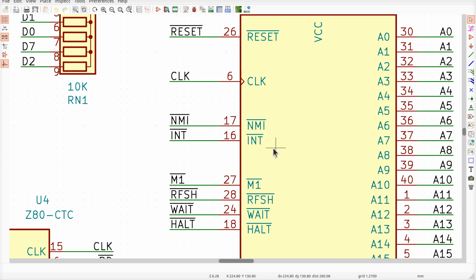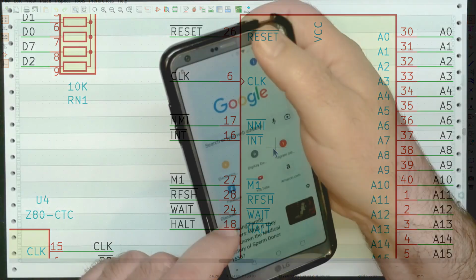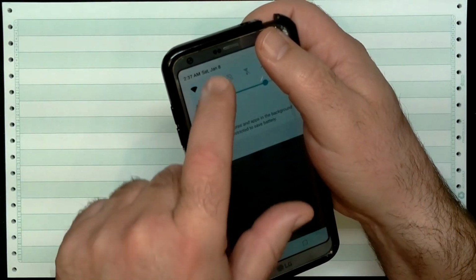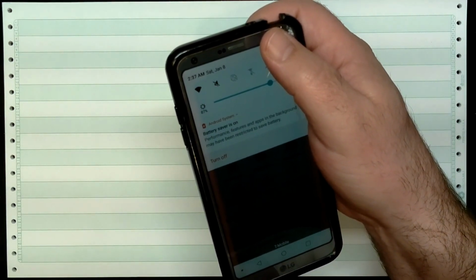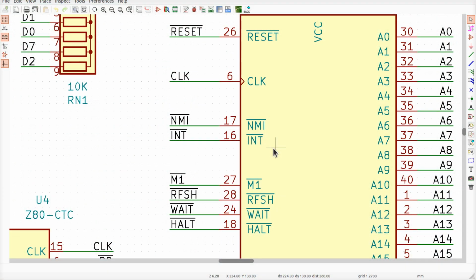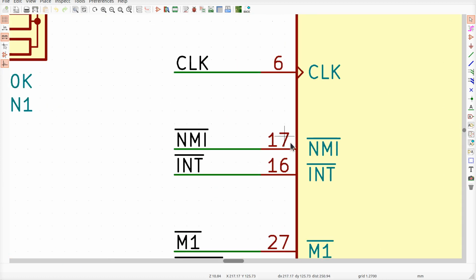You can either pick up the phone and handle it right now, or you can ignore it, or you can grab your phone settings and completely disable your phone from being able to alert you at all. When you do that sort of thing, that's what masking an interrupt is. Now obviously you cannot do that to the signals on pin 17, like I said before, but you can on pin 16, and that's the difference between these two.